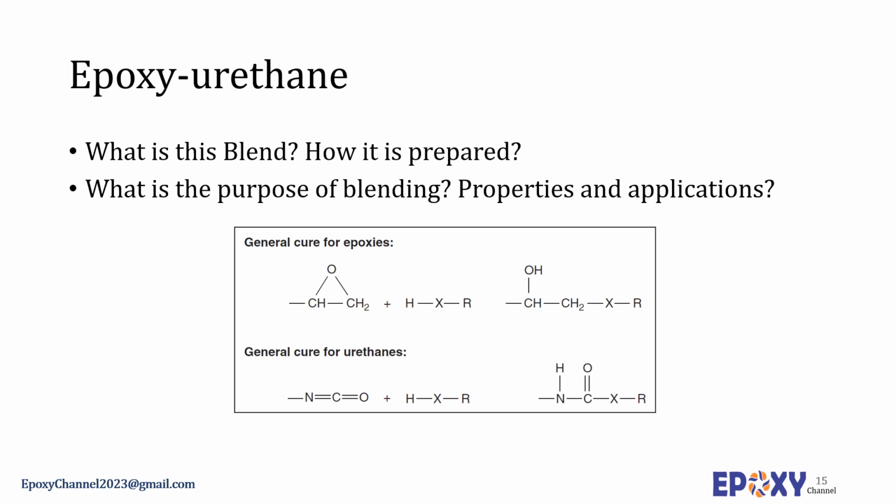The epoxy-urethane adhesive resists hydrolysis and gives useful bond strength up to 100 centigrade. The epoxy-urethane adhesives were developed initially for bonding to oily cold rolled steel, but they have given good results on other substrates as well. It is believed that the oil contaminant on the substrate is absorbed into the adhesives and acts as a plasticizer.